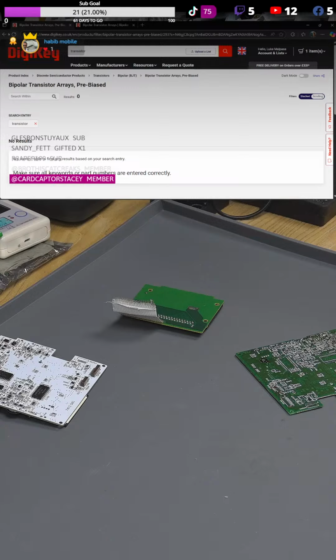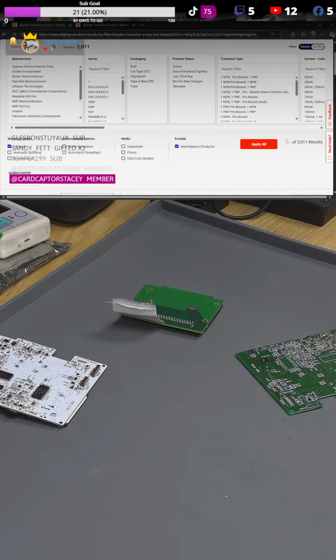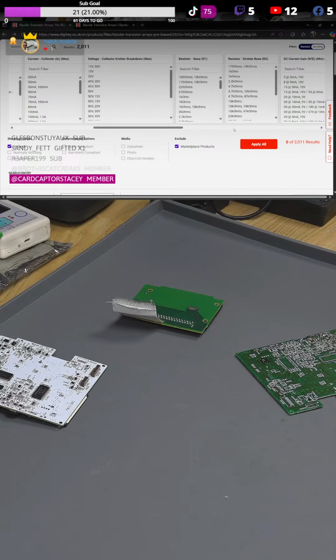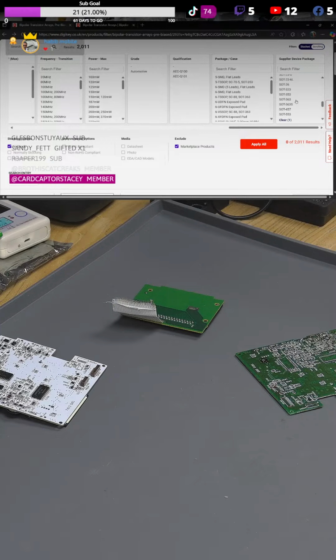So there's none in the SC74. So let me just pull up those SOT23-5 package alternative names. I can't remember what they are. There's the SC74, the SOT753 is another name for it. So let's try SOT7. Nope, can't see that. I wonder if we've got one in here. There we go, SC74A. Let's clear the other one, so use package case instead of that. And then the SOT, what was the other one? SOT753, which is linked there. So I'm pretty sure that's going to be the right filter for the package size.